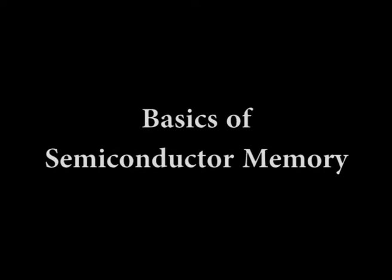Basics of semiconductor memory. Memory is the portion of a system for storing binary data in large quantities. Semiconductor memories consist of arrays of elements that are generally either latches or capacitors. As a rule, memories store data in units which have from 1 to 8 bits. The smallest unit of binary data, as you know, is the bit. In many applications, data are handled in 8-bit units called a byte or in multiples of 8-bit units.